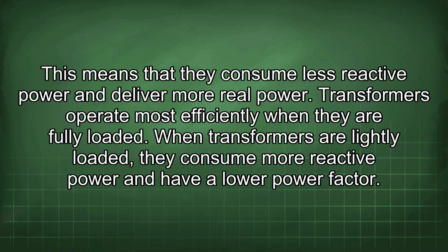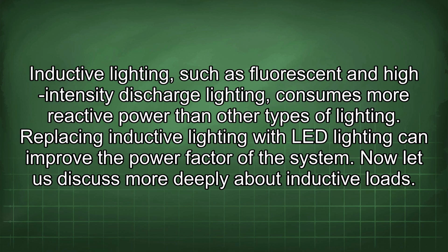Transformers operate most efficiently when they are fully loaded. When transformers are lightly loaded, they consume more reactive power and have a lower power factor. Inductive lighting, such as fluorescent and high-intensity discharge lighting, consumes more reactive power than other types of lighting. Replacing inductive lighting with LED lighting can improve the power factor of the system.